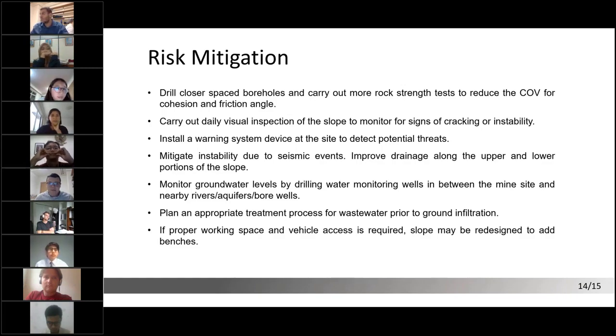Yeah, I guess if it was in an area where you would be expecting seismic events, it would be important to do some sort of test that would test how the rock would move down the boreholes. If it's mostly rock, we would be just taking rock samples. So you could take the rock out and then test the strength while it's out of the ground. But doing in situ tests would be important too.